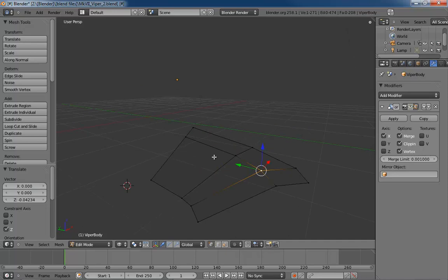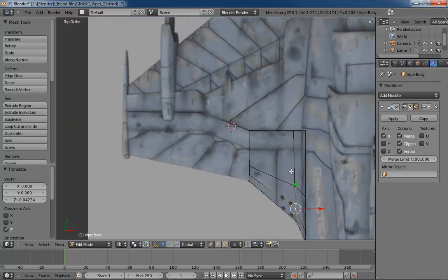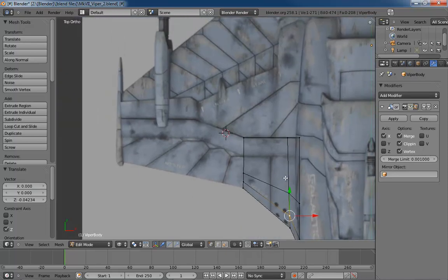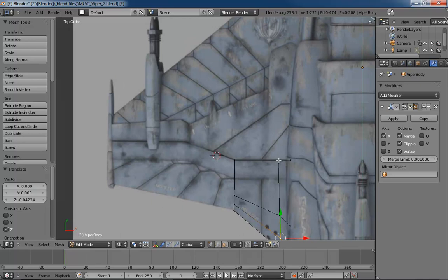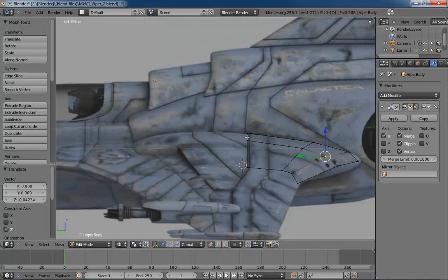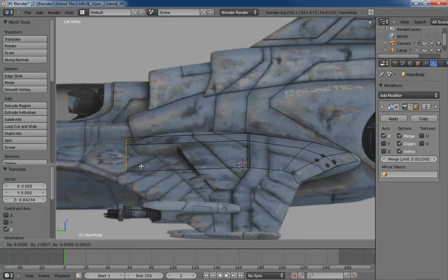Okay. So, back up to the top view. Things looking pretty good so far. And from the side view, things also looking good. Let's build forward and then I'll build outward. So we'll hit Control Tab E for edges. I want to grab these two front edges. We'll hit the E key to extrude, and I'll pull them to right about here.